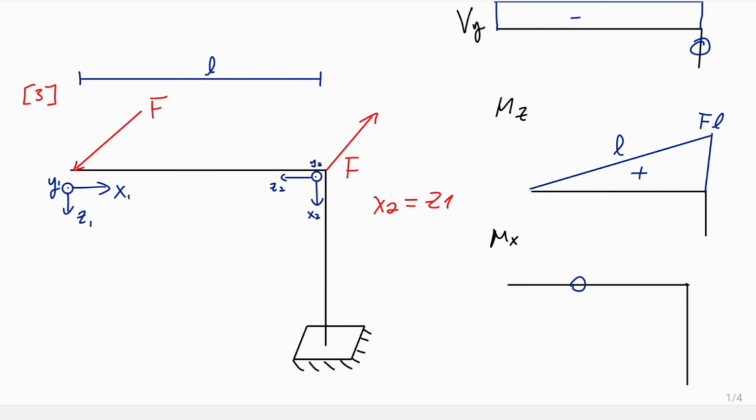But what we define that direction as does change in this beam because the axial direction always has to be x. So now this z moment has to be transferred to the x direction, and it transfers directly because the sign doesn't flip, the x direction is not pointing upwards. Therefore, this part has to have a torsional moment of positive FL. And this completely makes sense from what our intuition said, because I told you that we have a torsional moment caused by this one crossing this direction. F crossing L gave us this torsional moment, which is exactly the magnitude of the torsion we have.